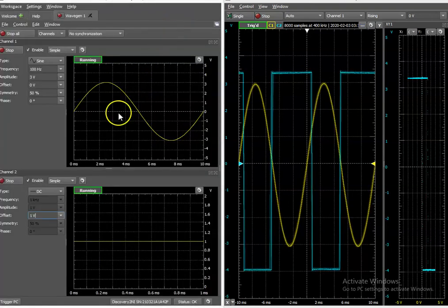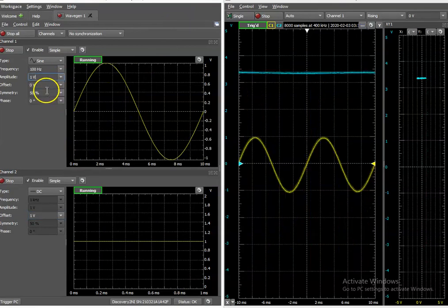To know the importance of amplitude of the input signal, reduce the amplitude of input sine wave to 1 volt. Notice that the output stays either at plus Vsat or minus Vsat. This is because the input amplitude is not crossing the threshold voltage of the circuit.